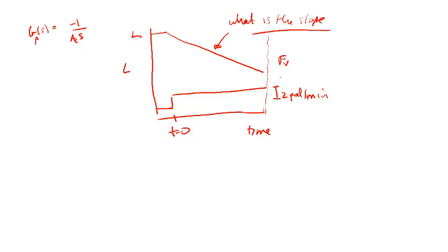Another question I could ask is, what is U(S), or F(S)? So what is the input in the Laplace domain? The input for a step change in the Laplace domain would be 2 over S.